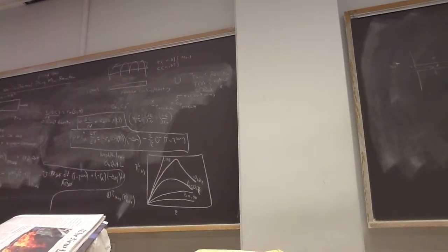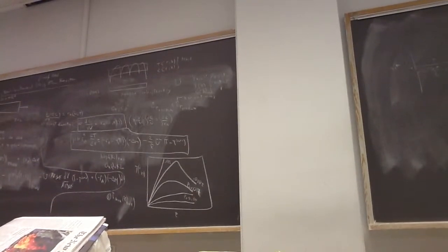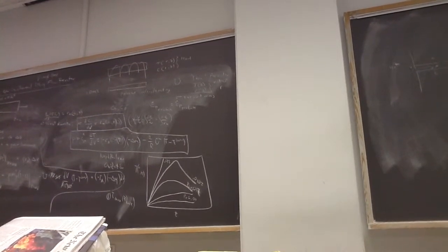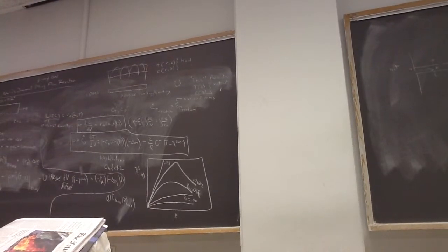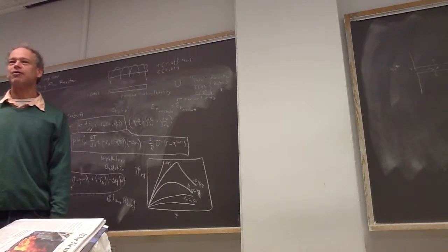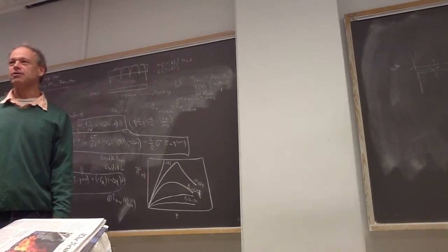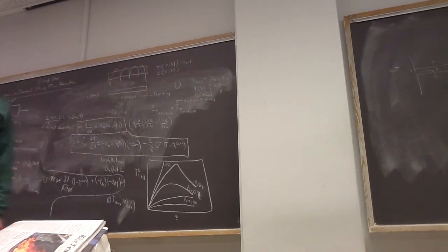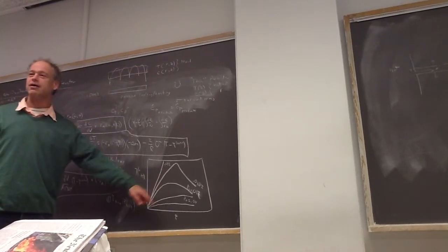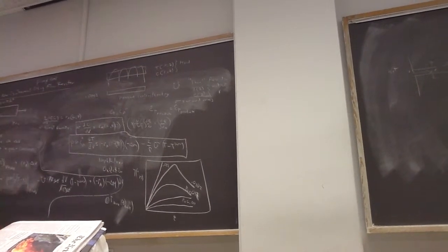So what this curve points out is that being a chemical engineer, designing a reactor, is a dangerous business. You really have to know what you're doing if you have exothermic reactions. If you have a very exothermic reaction, that's known as a bomb. So what you don't want to do is make a bomb. You want to make the product of naphthalene oxidation.